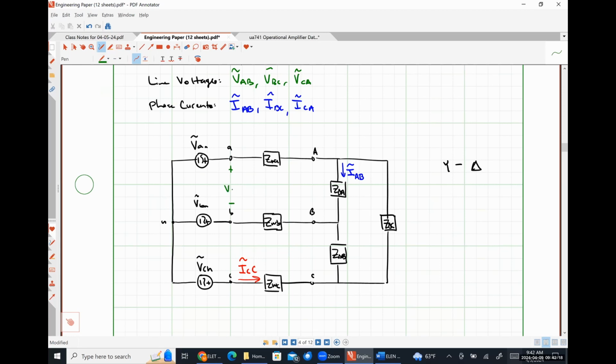What about this voltage VAB? So that is a line voltage because it's measured between the transmission line terminals of the source. What about this voltage VBC? It's both. It's a line voltage and a phase voltage because it's delta connected, and the line voltages and the phase voltages are literally the same for a delta connected thing. Okay. So you were both right.